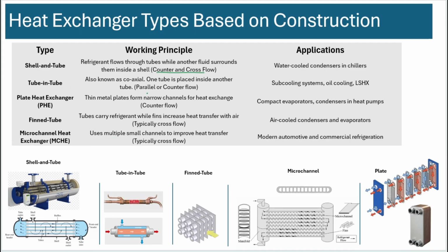Tube in tube could have parallel or counter flow. An example is this, but the majority of the time it is designed to be in counterflow. Applications include liquid suction heat exchangers, subcooling systems, oil cooling, etc.